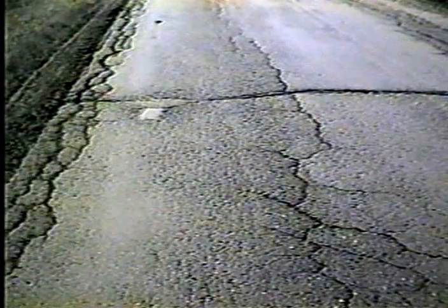We see other examples of longitudinal cracking. Oftentimes they'll first occur along the edge of the pavement, where you have an unsupported edge. Heavy traffic loads moving along can cause load-related distress along the edge of our pavements.